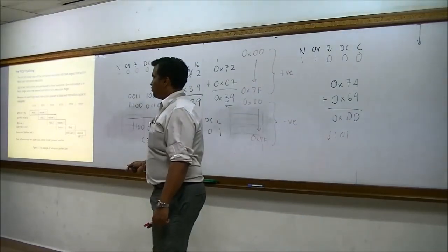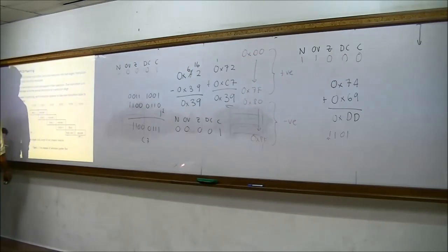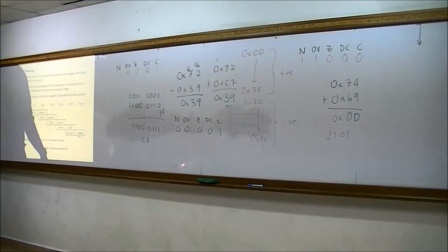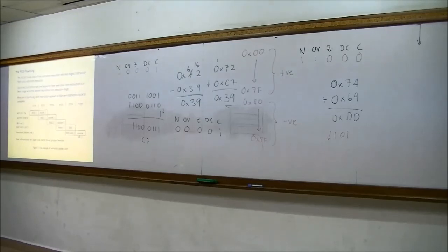Now assuming that you have written a few lines of instructions, we're going to see how these instructions are executed. This TCY means time clock cycle. Time clock cycle is like the base time for your digital hardware to work. For example, your watch: what is the base time of your watch? 1 second, right? Every second is the base time of your watch. What's the base time of your laptop? Take the frequency and divide: 1 over the frequency, you get the time. So you know how fast your processor works, right? Like that, you have every tick, like how your second is ticking.